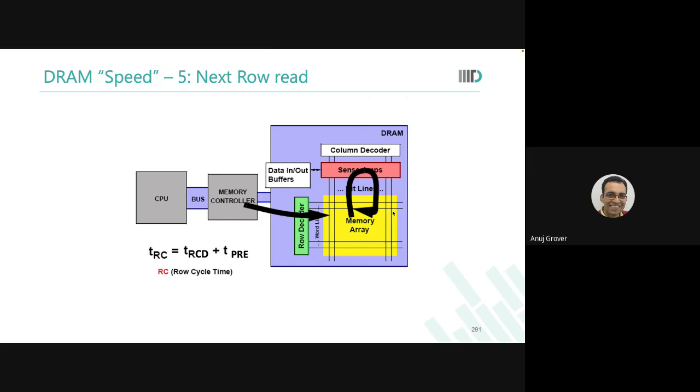Also, late is useful when we know the address before that, before we want to process the data. Late is useful when, as I said, you have multiple dies sharing the same output bus, and you get the output enable when you are done. After the row access, you get output enable later. So this will ensure that a large number of dies can be supported. Overall capacity can be increased, regardless of the technology that we design. Is that okay until now? Any questions?